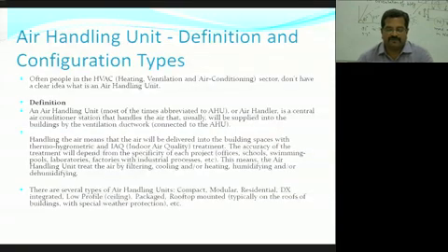There are several types of air handling units: compact, modular, residential, integrated, low profile. It means it has to be hung from the ceiling, packaged, rooftop mounted, typically on the roofs of the buildings with a special weather protection.